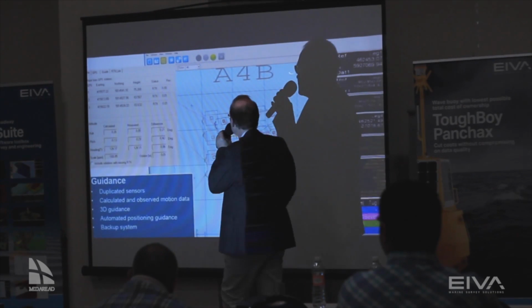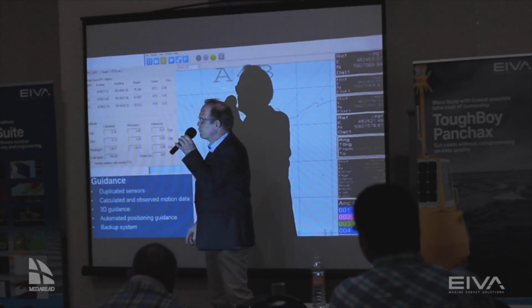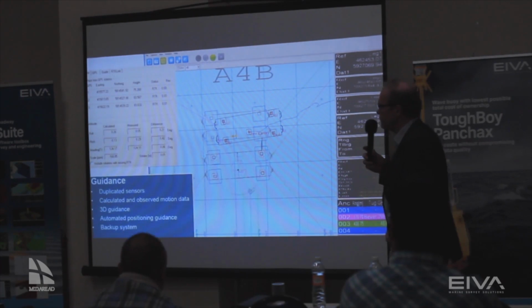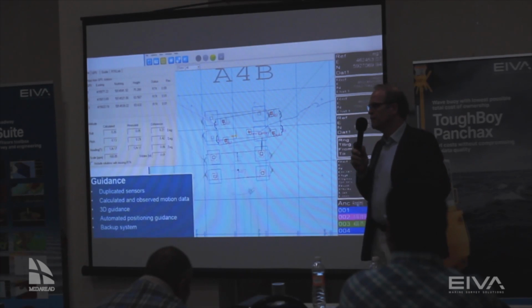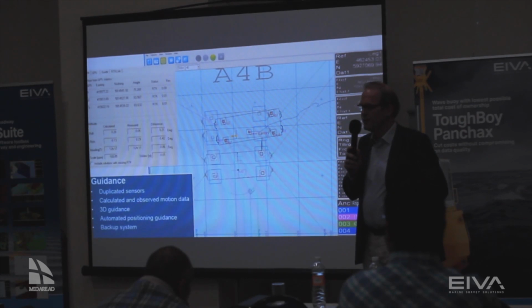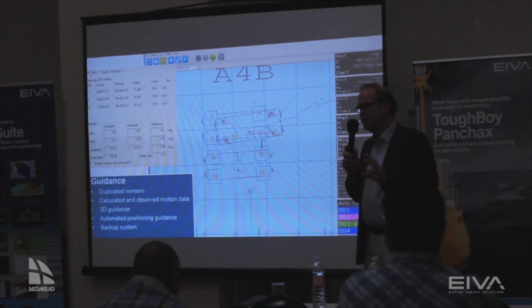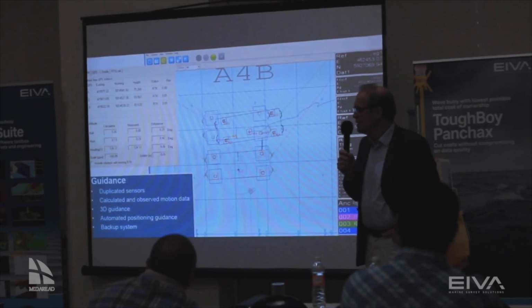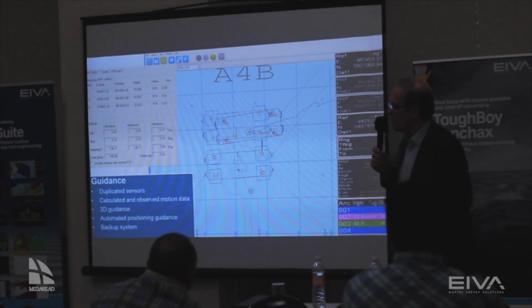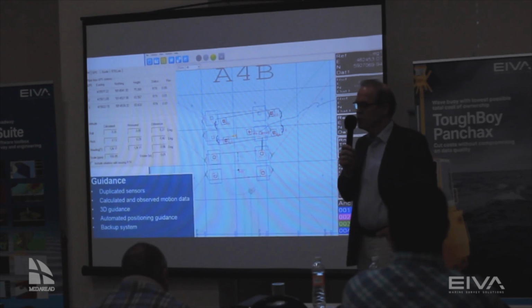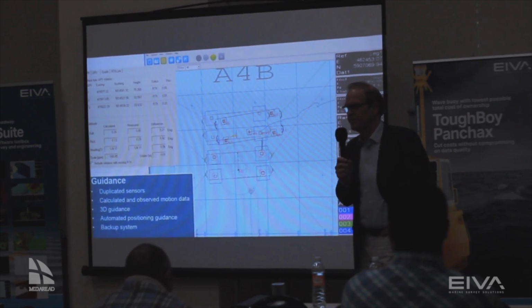And on top, you see that this platform is equipped with 3 GPS antennas. But these kind of operations can only work if you have a very accurate GPS. That means normally you need an RTK solution, that means around 20 to 30 centimeters of accuracy. This can be either achieved with a RTK reference station, or you use satellite corrections, for example.